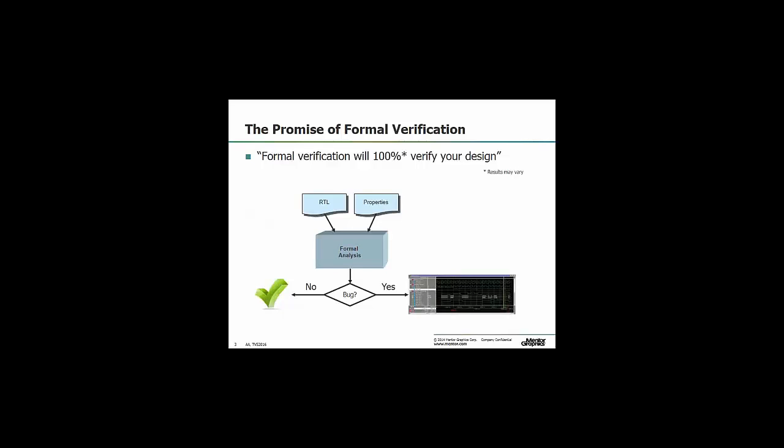The goal, of course, of formal verification is to have 100% verification of your design. Formal verification can be seen somehow as dual to simulation. In simulation, you provide RTL and stimulus, and the simulator tells you what behavior results. In formal verification, you have the RTL, you specify the property or the behavior that you are looking for, and the tool provides you the stimulus. So it's a little bit mysterious, but the tool is what gives you the stimulus.